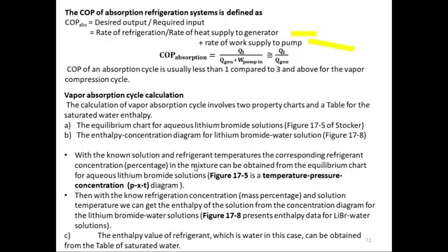The temperature you can measure. The pressure, because both of these tanks, the lithium bromide and the water, are connected to each other, at a given temperature of water, you will always know the saturated pressure. That same saturated pressure will be in the lithium bromide solution tank. So we know the pressure in that fashion, and we can measure the temperature. If we know these two things, then using the chart we can determine the percentage of lithium bromide in that solution.